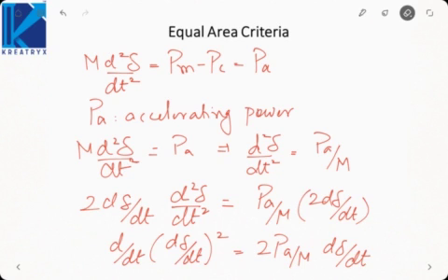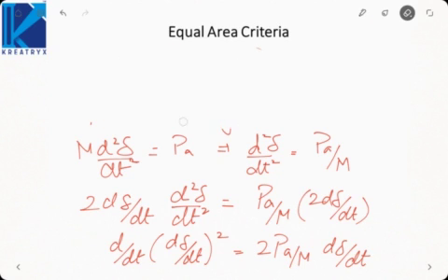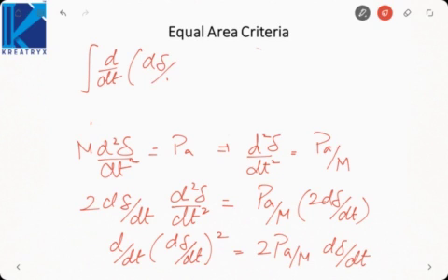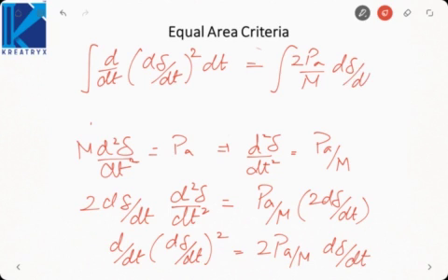Now if you integrate both sides with respect to t, the integral of d(dδ/dt)² should be equal to the integral of 2Pa/M (dδ/dt) dt.